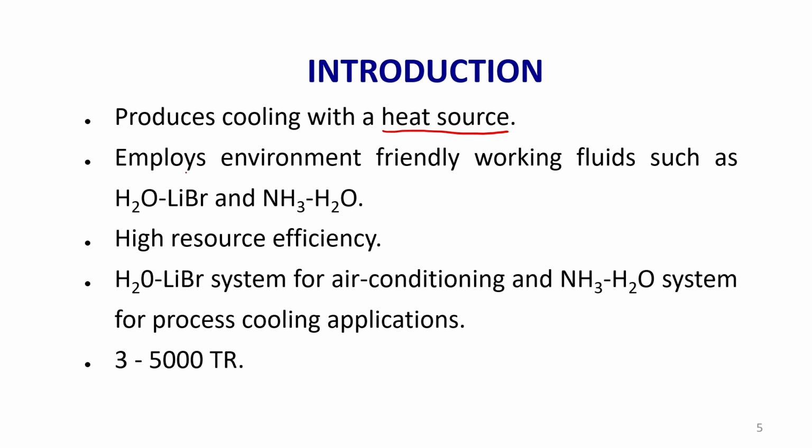So, this absorption system does not require electricity except to a smaller extent, to a smaller magnitude. And as far as the working fluids are concerned, it employs two types of working fluids. One is water lithium bromide and another one is ammonia water. In the water lithium bromide system, water is the refrigerant, and in the ammonia water system, ammonia is the refrigerant.